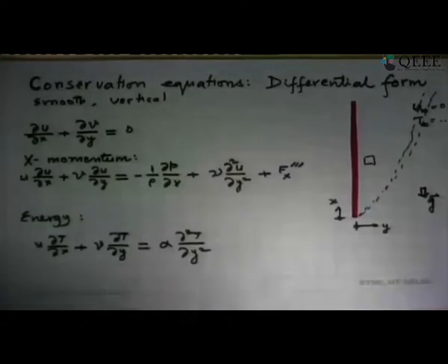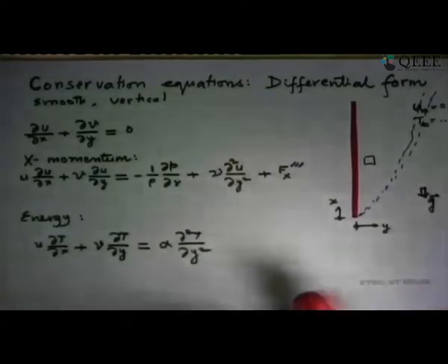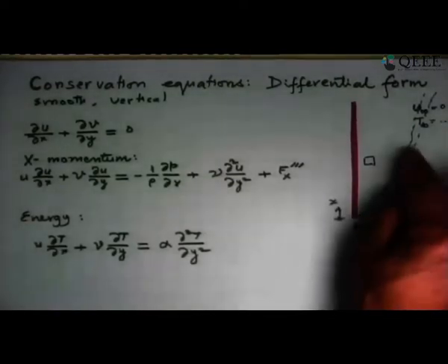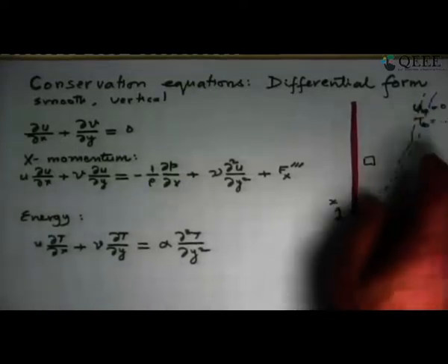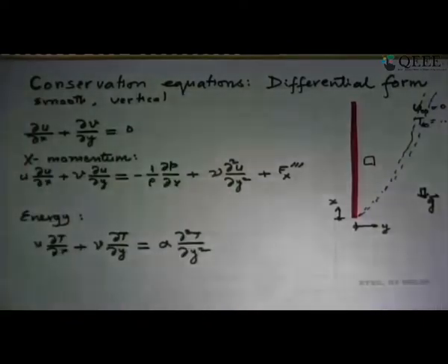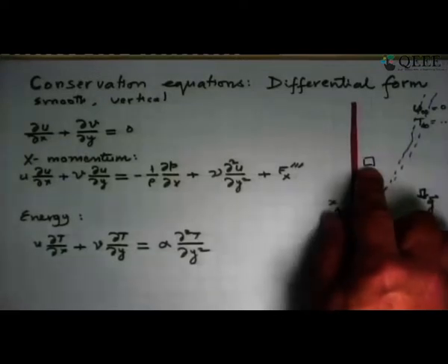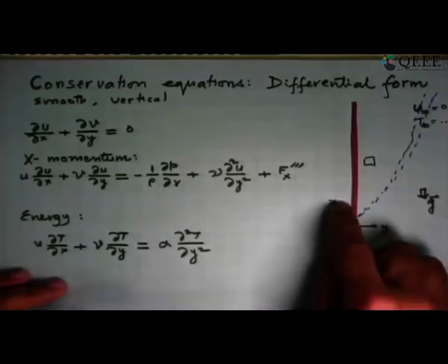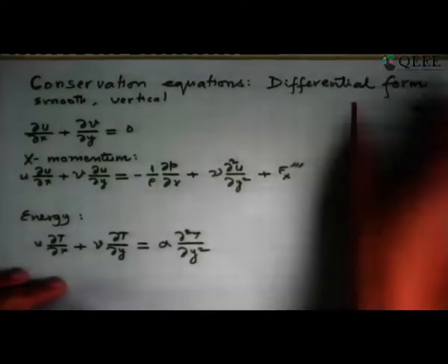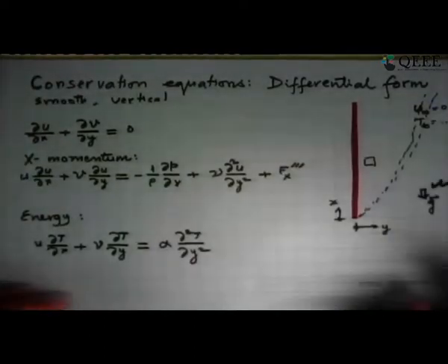And the reason is that fluid velocity is sustained by temperature difference. If there is no temperature difference, the fluid will not be in motion. So outside this there is no motion. Close to that, only because of some inertial and drag forces, this fluid, which was at higher temperature, actually pulled out this fluid because of viscous force. But that's small. So we take this element and say, what are the conservation equations for this element? Our coordinate system is that normal to the plate, this is y. From this thing, upward direction, we have x, and the whole thing is being influenced by gravity. So this is the reason for this.